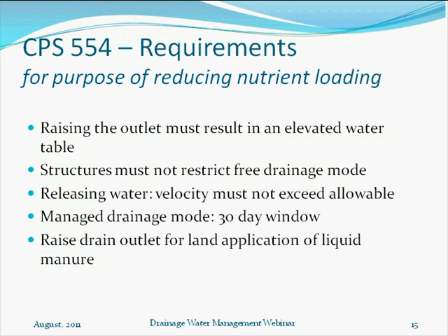When you don't want to do any kind of management of your drainage and just let it drain freely, any structure that you have put on there must not restrict that free drainage. Releasing water, you need to make sure that you still meet the practice standard for Conservation Practice 606, subsurface drain. There are provisions in that standard about velocity and tile, as you might recall.